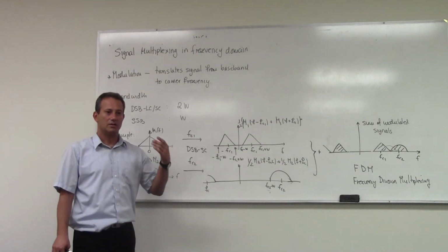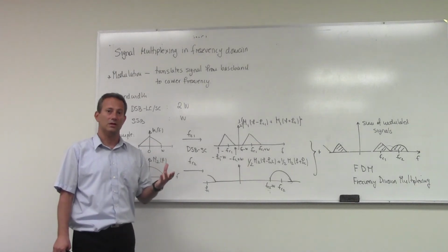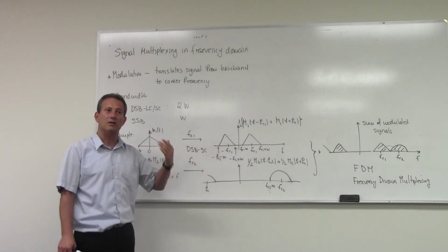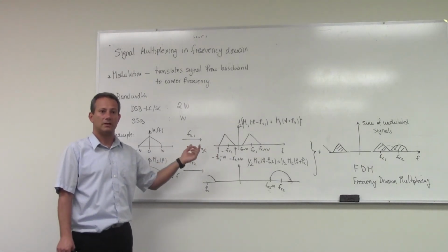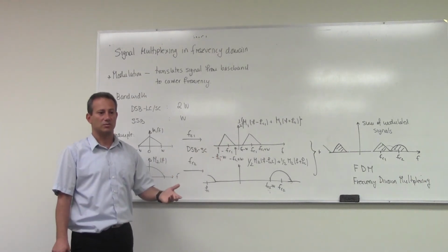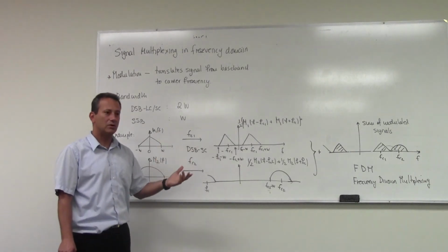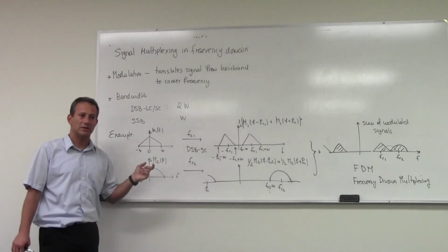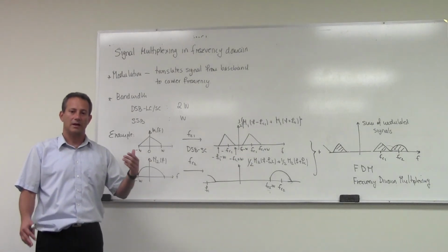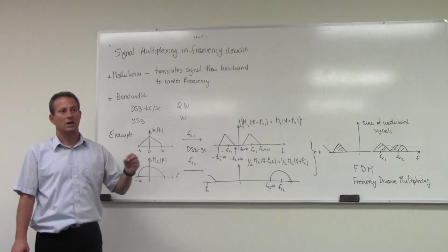Okay, so that's the story of the single sideband. In summary, it's a very efficient modulation. It does not use more spectrum than what is absolutely needed. You cannot eliminate more than a sideband, because then you're eliminating information. But adding anything beyond a single sideband is adding redundancy to your transmission. So it's as efficient as it can be, but it's relatively complicated. You have to do a lot of processing at the baseband. You have to make sure you have a Hilbert transformer at the baseband. And you will see later in this course, it is very sensitive to the noise.